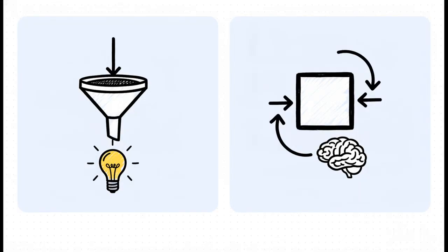And that brilliantly illustrates the second part of our definition, sequential circuits. Think of a combinational circuit, like a standard AND gate. It has absolute amnesia. It's just reacting to current inputs, kind of like real-time math. You change the input, the output changes instantly, no memory whatsoever. But a sequential circuit, like our flip-flop, introduces the concept of time into the equation. Its output depends on the present input and its previous history. It literally physically remembers what happened a moment ago.